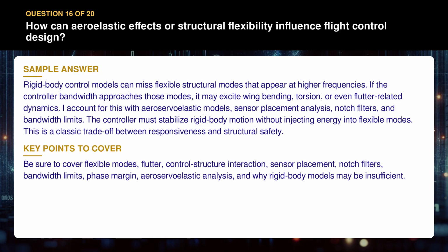Be sure to cover flexible modes, flutter, control structure interaction, sensor placement, notch filters, bandwidth limits, phase margin, aeroservoelastic analysis, and why rigid body models may be insufficient.